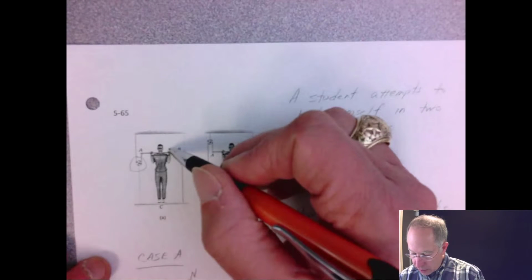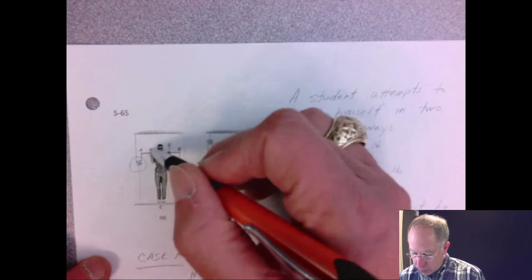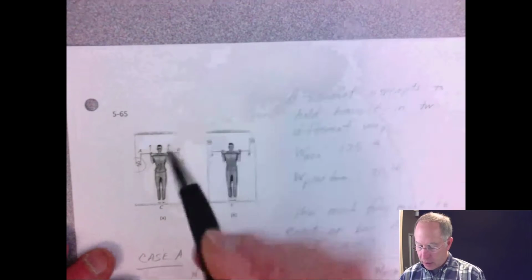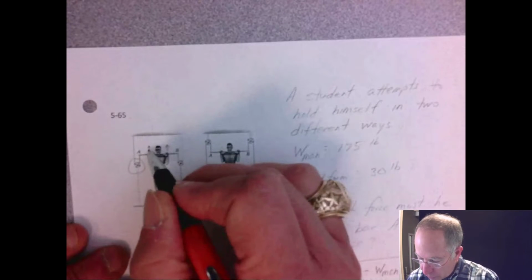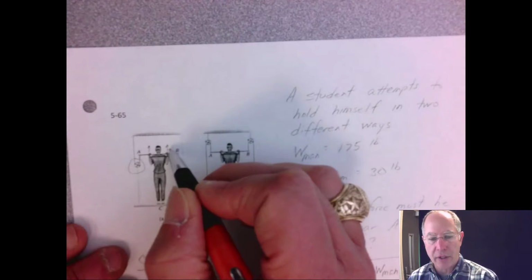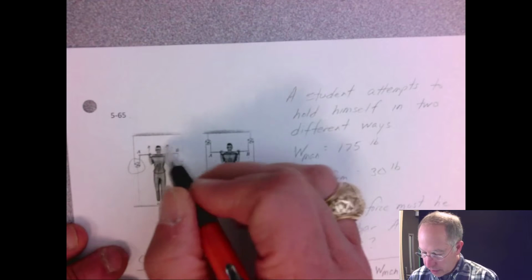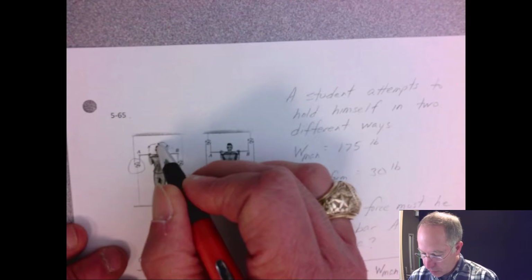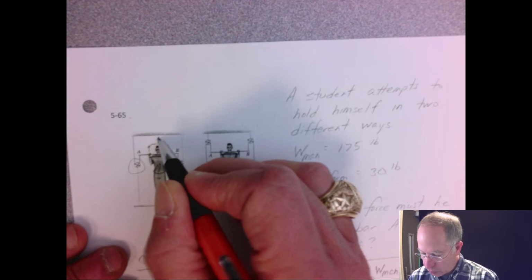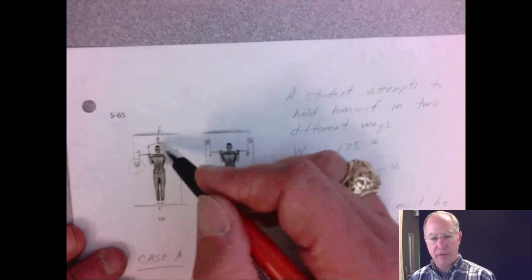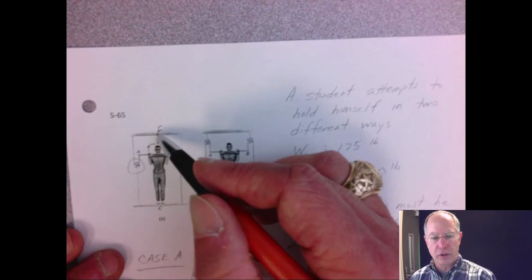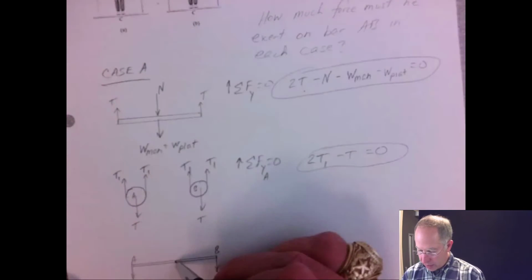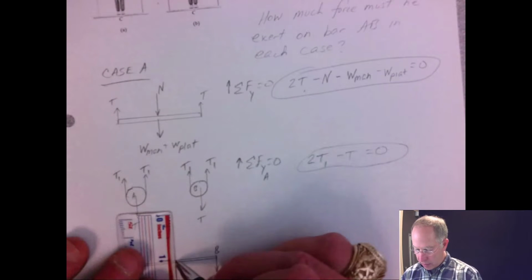So you have a force here and a force here. Basically, this is half the component force here and half the component force here, and together the resultant force is just F going up, half of it in each arm. But we'll just take the resultant and put F right in the middle of that.